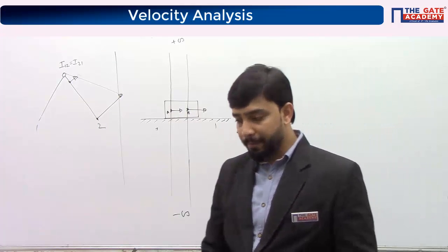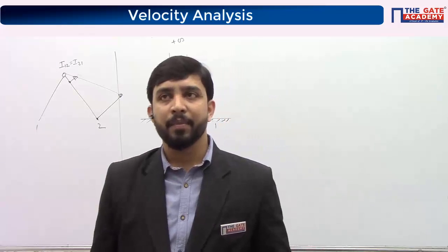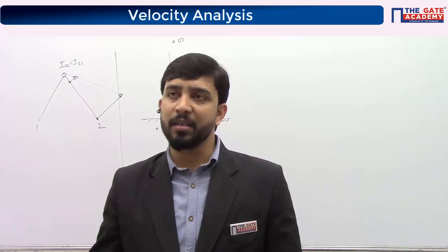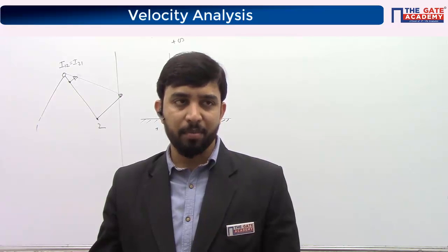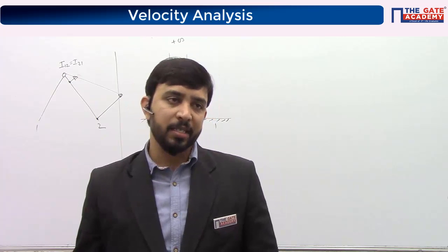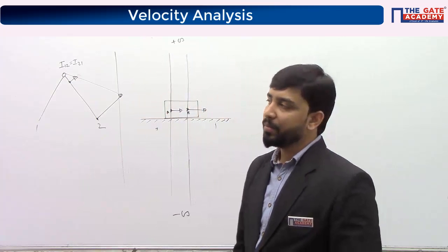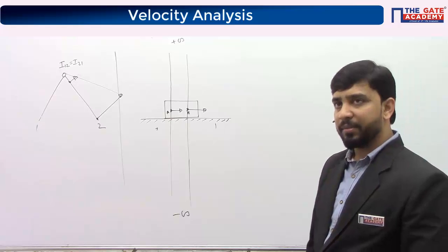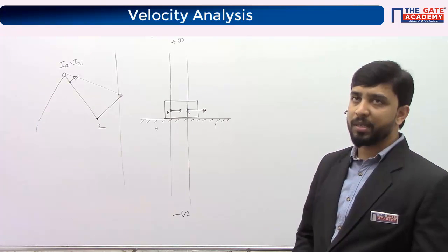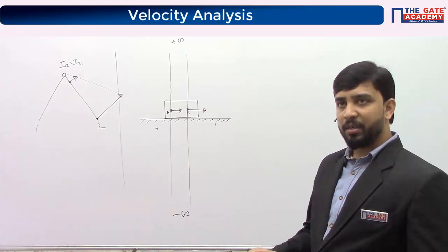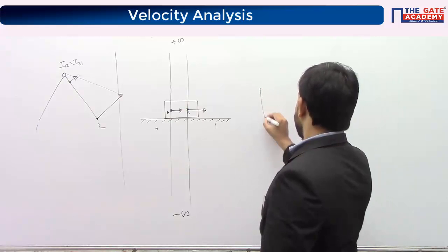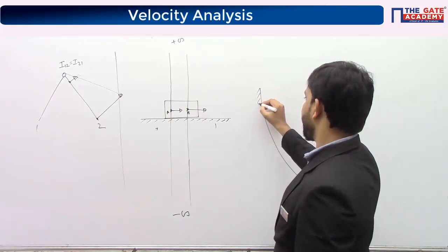For a sliding pair, the I center lies at infinity in the direction perpendicular to the plane of sliding. So it lies at infinity, but the direction is perpendicular to the plane of sliding, okay? So try to locate the instantaneous center for this case.